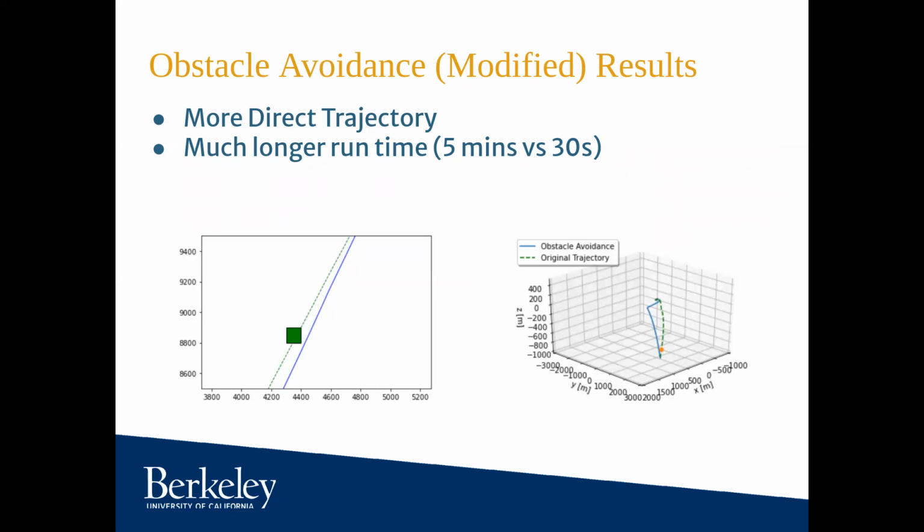In this case, we're doing 120 samples, but our sampling time is 1 second, and so we're only able to do one of our impulses in this time. So we only get to predict one optimal U, and that changes the trajectory a little bit.